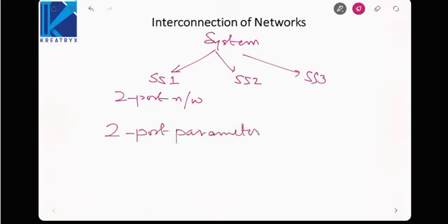Now when multiple systems are connected with each other, the challenge lies in identifying the parameters which will give us an advantage. Like if the networks are connected in series, then their Z parameters can directly be added. So it is better if we deal in terms of Z parameters. If they are in parallel, then Y parameters are added. So it is better I deal in the Y parameters. So the only thing that we need to identify is which parameters are advantageous to use in various scenarios. There can be various connections like cascade, series, parallel and series-parallel. In each we need to find the parameters that give us an advantage.